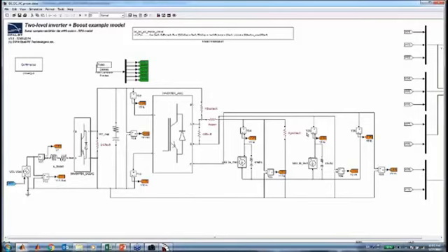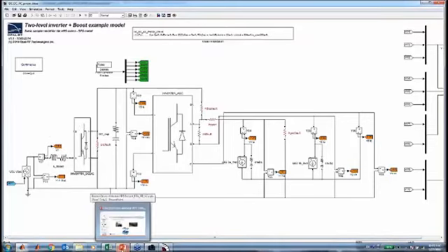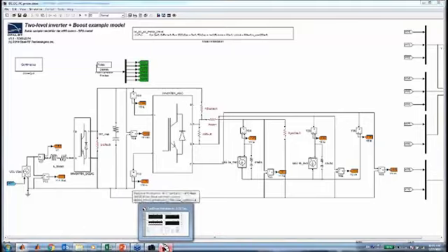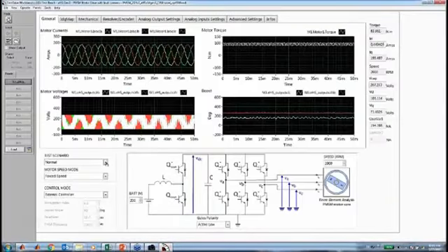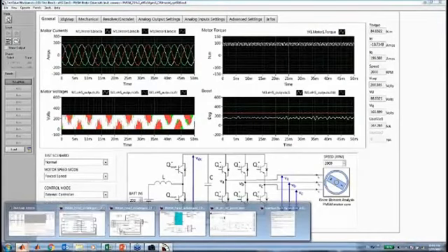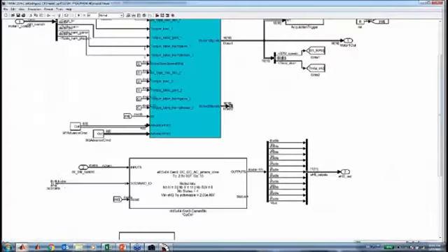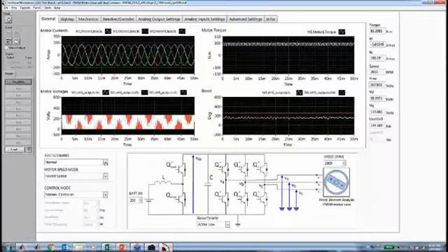The other thing is if you want to change, for example, the impedance of the boost capacitance on the fly, or make a very big boost inductance variation, this is something that's possible, and this is something I'm going to demonstrate as well. So if I come back to the model here, I linked my scenario to that button here. In the CPU model, I have an input here, and basically I'm going to control that constant, which is a scenario ID, on the fly from the test drive panel.